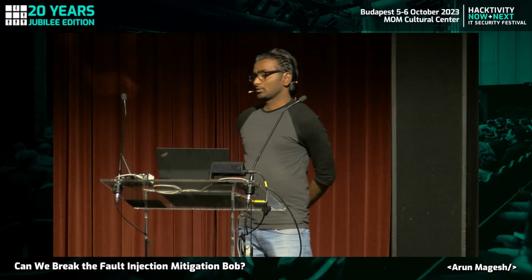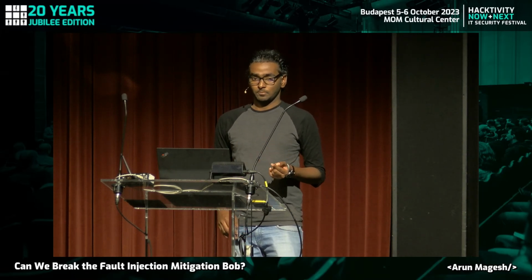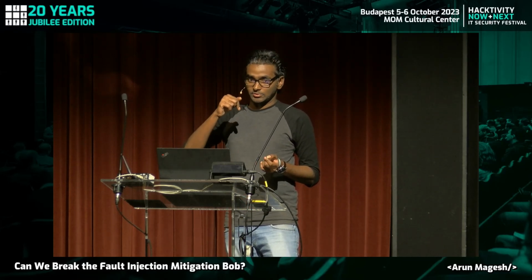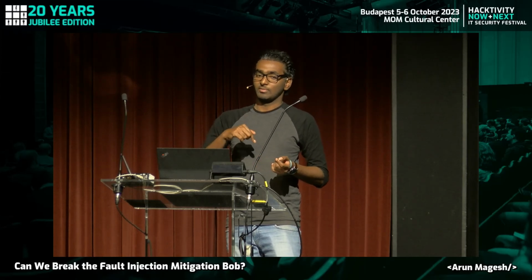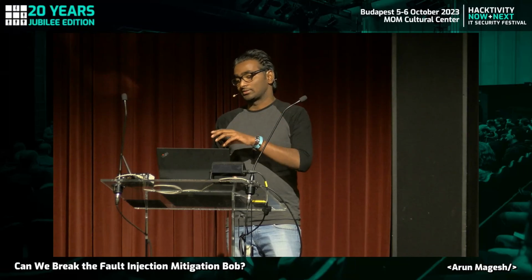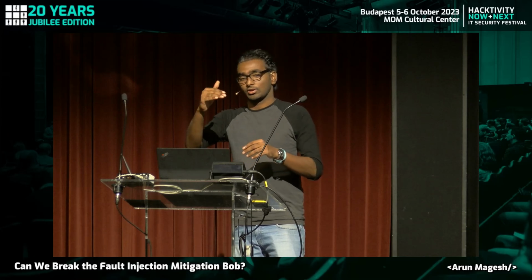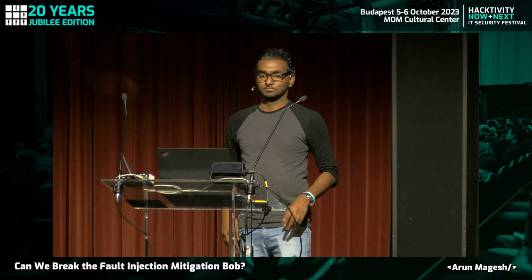Yes, that is one of the mitigations. But the problem is that it only mitigates voltage-based glitches. If the voltage doesn't work, then I can go for EMFI, where I use a small coil and glitch directly on the CPU. Or you can also use a laser, because with a laser you directly hit photons on the metal layer and create charges. So they help in mitigating, but they don't necessarily mitigate completely. Even if you have a capacitor, you can use a powerful glitch. Instead of shorting it to ground, you can also short it to a negative voltage so that you drain the capacitor way faster, and then you can still inject the glitch.